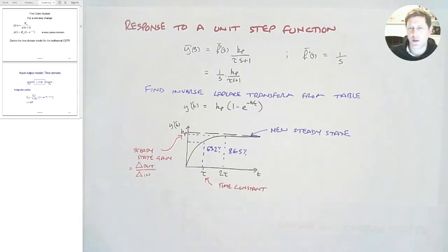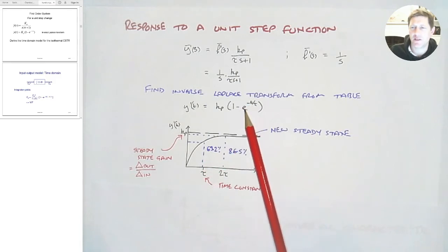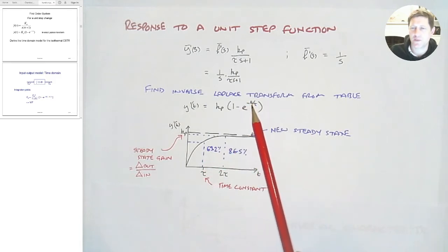So what does this look like? If we're plotting the deviation response y dashed against time, at time 0 deviation will be 0 because it's coming from a previous steady state condition. But then there's a step change to the input, and so the system starts to respond to that. So it responds, it gets larger, and then as time increases, the e to the minus t term starts to dominate.